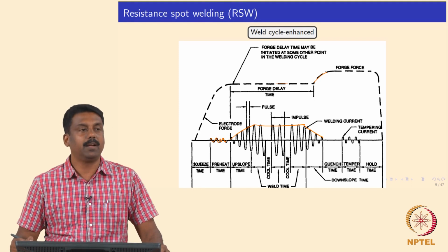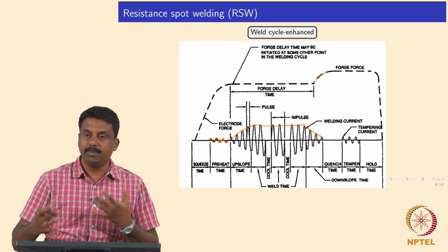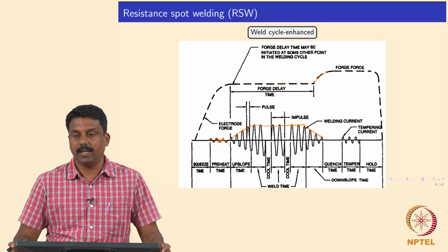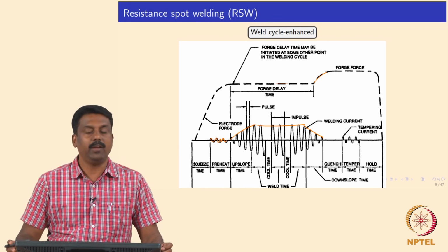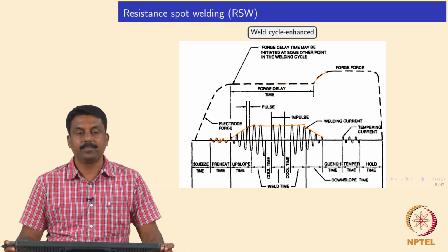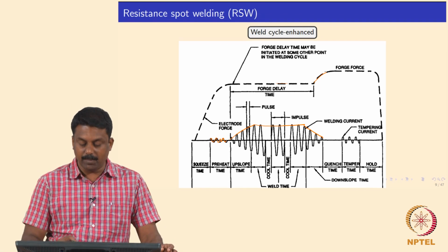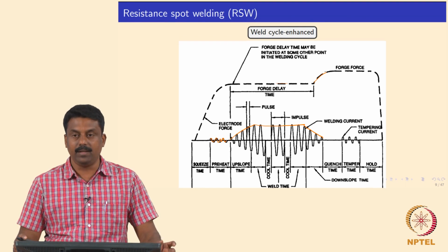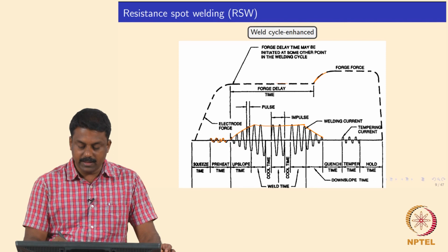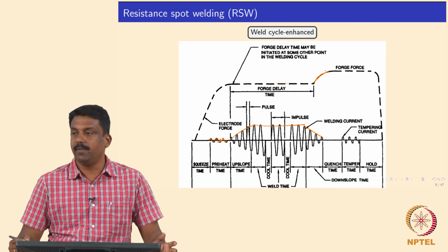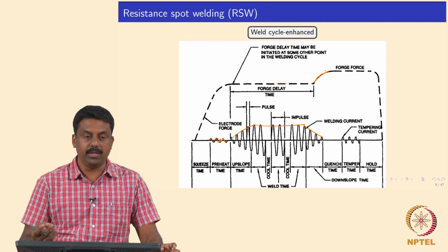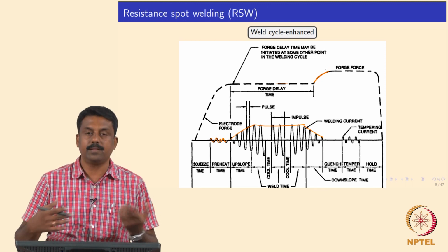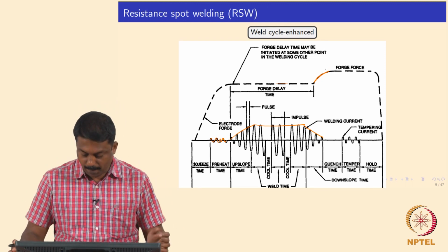It is also beneficial in order to mitigate the residual stress that is forming during welding, say when the martensite forms. So, you have a tensile expansion, and you can also accommodate that by applying a compressive force. In order to reduce the residual stress development in the weld, subsequently when the weld nugget is cooling down to room temperature, you may also increase the load in such a way that you apply a compressive force to mitigate the tensile stress that is developing in the microstructure, right.